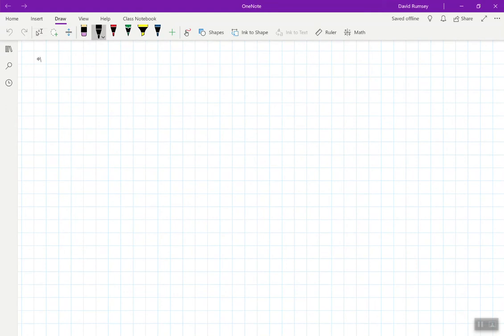And recall that for an RC circuit, the time constant is R times C, and for an RL circuit, the time constant is L divided by R. Now I am going to do two circuits here to demonstrate how to measure time constants. The first one is going to be very similar to the ones you do in the lab.